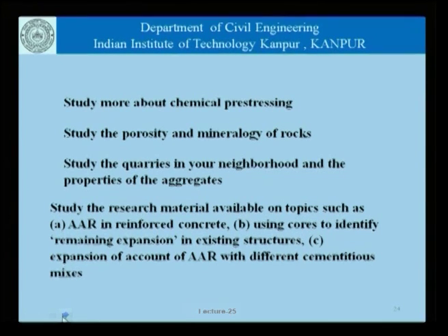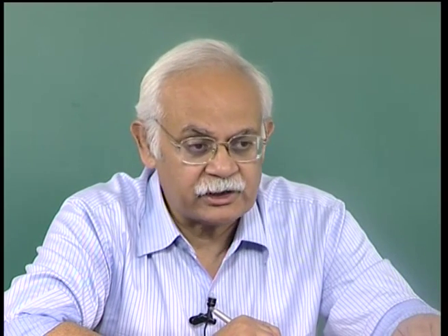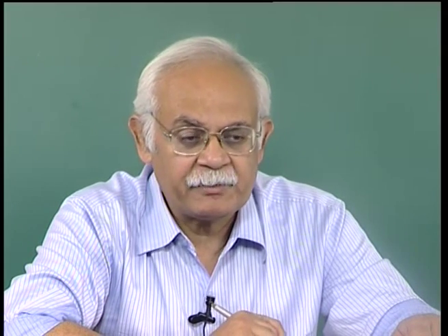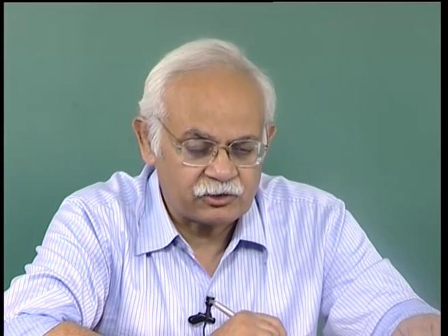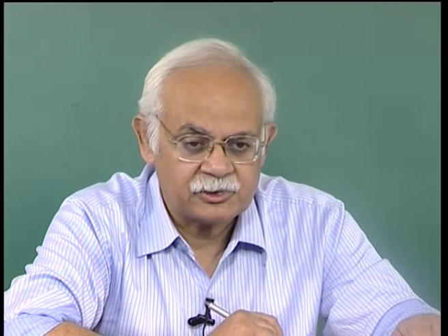And that is the kind of discussion which we were doing, or which is relevant from the point of view of controlling the expansion on account of alkali aggregate reaction by manipulating the cement content or the alkali content in the cement, controlling the cement content, using chemical admixtures or mineral admixtures to control the overall alkali content in the concrete.